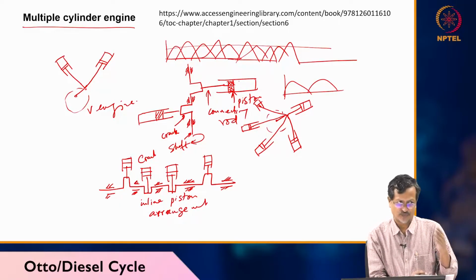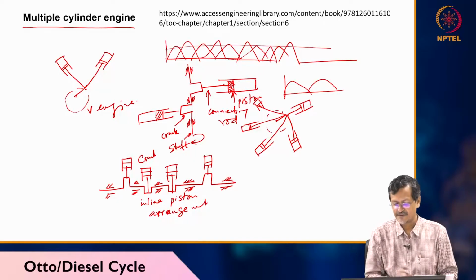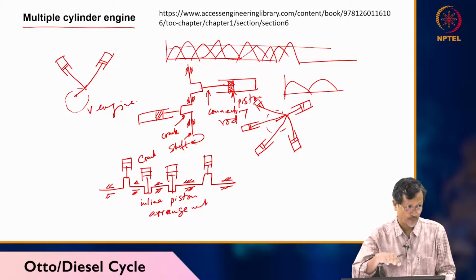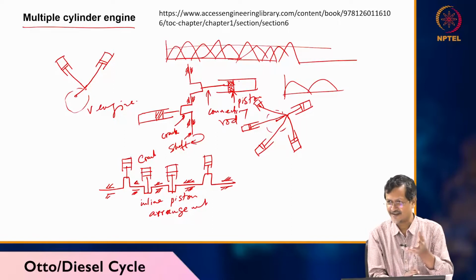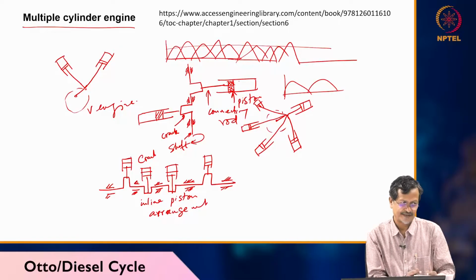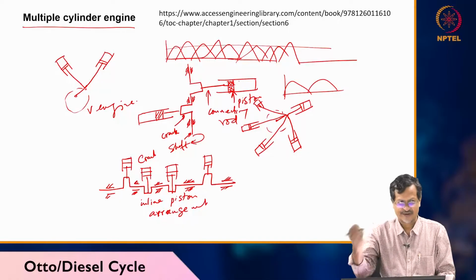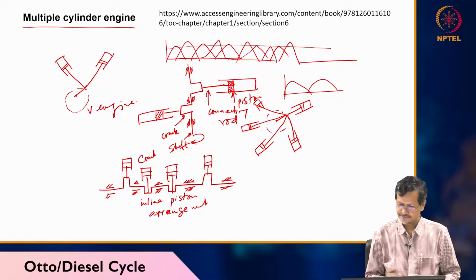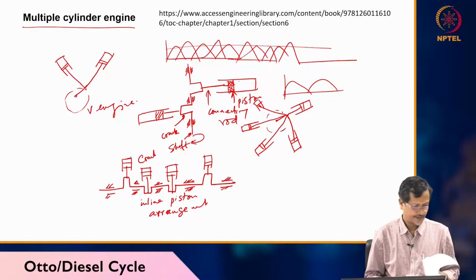So a flywheel works, and for smaller applications, like a small engine, a flywheel is okay. But when you need big power, for a cargo ship, a train, a truck, in that case you need multiple cylinders. That will smooth the power and your flywheel requirement will be lower. A flywheel means heavy mass you are carrying unnecessarily, right? On a heavy machine like a truck, instead of carrying the heavy mass, you make multiple cylinders, and you get higher total power. Okay, this is done.